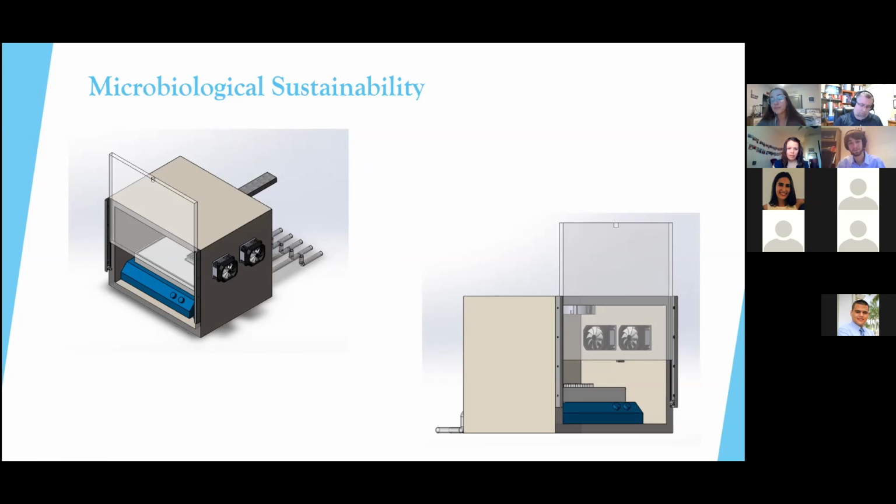So I understand that you have the 5 tubes for each of the individual gases, but where do you vent the exhaust gas is my question. So sorry, yeah, the exhaust gas is actually vented through that centrifugal fan. To like an external waste bottle or into the container? Yes, to an external laboratory waste bottle. The gas coming in is through the mass flow controllers and the tubing. And then the excess gases are expelled using the centrifugal fan and outflow. So are you guys assuming that the lab's going to have capabilities to pressurize the waste bottle, or are you guys containing the waste bottle?